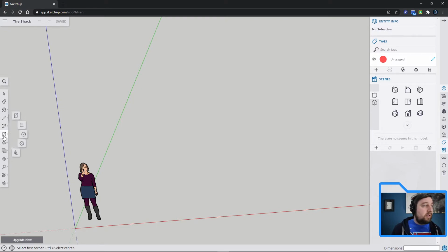But I'm going to click on the rectangle first. And you'll notice when I'm drawing, it's blue right there. That means I will be drawing in the blue plane, which is the z-axis plane. So that's correct for this case. But oftentimes it doesn't do it right, and you should get into the habit now of changing your scene to the view of the plane that you're drawing in.